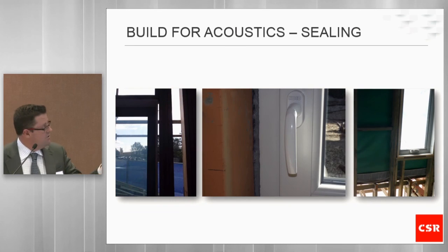We also make sure that the gap between the door and the frames, or windows and frames, are actually sealed. And as I said, that the building membrane is properly wrapped around into the frame of your window and door openings and sealed and taped off. This is really simple stuff, right? We don't have to do anything major. It's just doing things a little bit better than what we currently do.